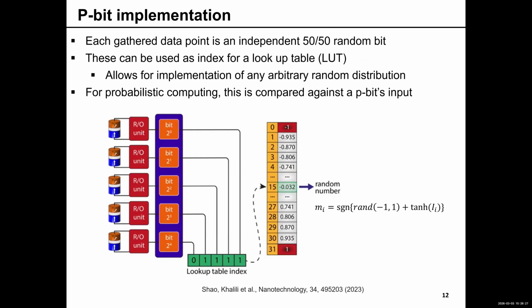Now, the question is then, how can I do probabilistic computing with this? Because if you followed the reasoning of the previous slide, basically what I showed you is essentially a coin flip device. It's a device that generates random bits, but they're really random with a 50% probability. And one of the things about these voltage-controlled magnetic tunnel junctions is that since they are voltage-controlled, we designed them to be more like capacitors. So they have a very high resistance, unlike spin transfer torque magnetic tunnel junctions that have low resistance. Which means that we cannot, at the device level, really tune the probability in any efficient way.